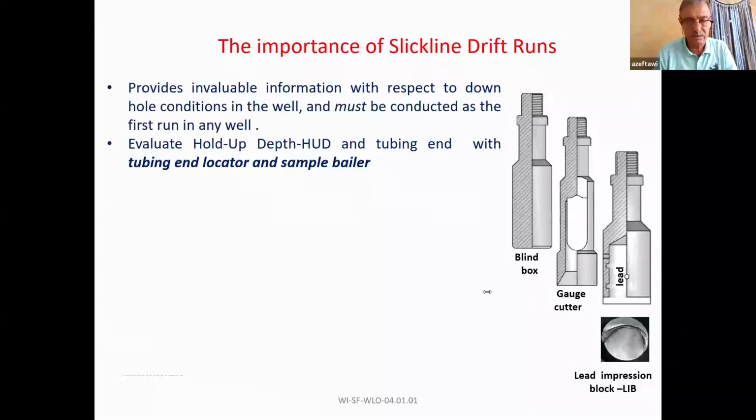Again, during your previous lecture, you said a riser is different from a lubricator because of flange connection. Yes, I did. So is it right to use a lubricator as a riser in a wireline or slickline rig up? Up till today, we said a lubricator is a threaded connection.